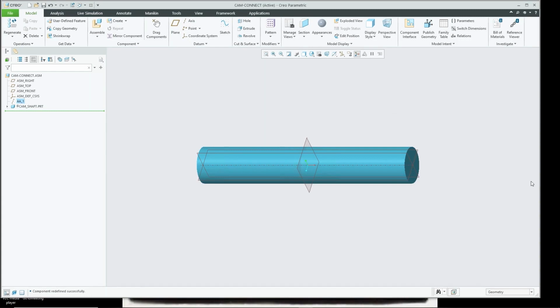I'm sorry, there was another question. Is there a similar function for using roller chains instead of a belt? I think the functionality is the same thing, looping. You may end up having to create a surface in the middle of the teeth to define where the chain link is going to be.